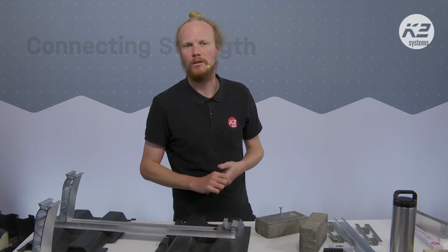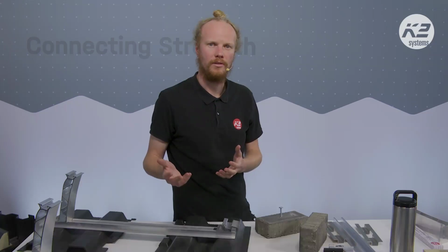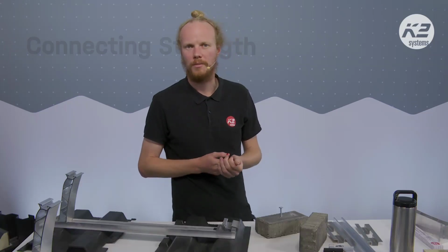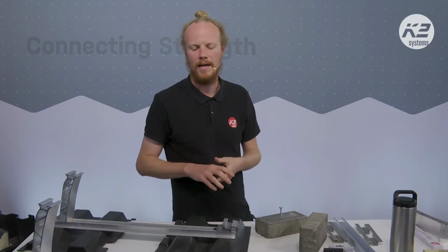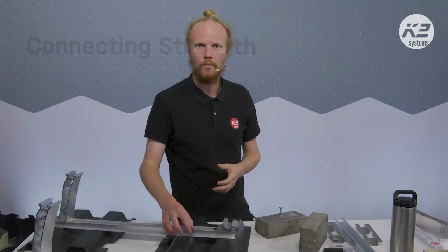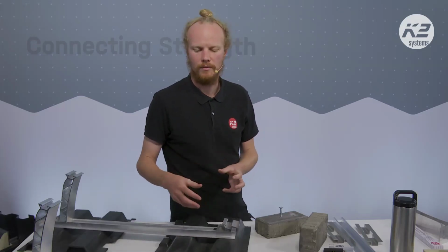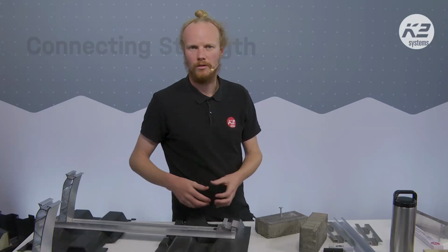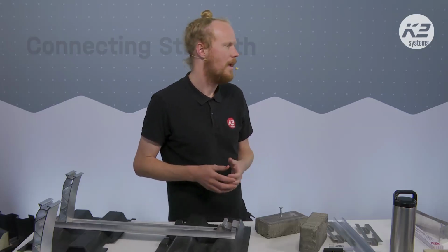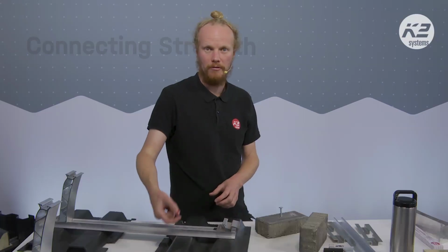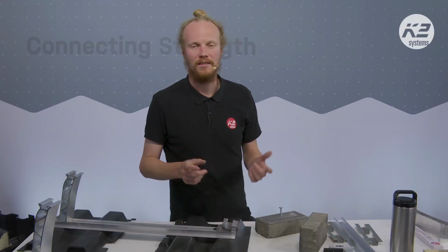So if you're unsure and they give the 2 values, always use the lower value. It's the more conservative value. And if you have a situation where it's dry for an extended period of time and the roof begins to dry out, you want to ensure that the ballast in the system is using the least amount of ballast per centimeter up that's necessary. So this density, if there's a dry one and a wet one, use the dry one.